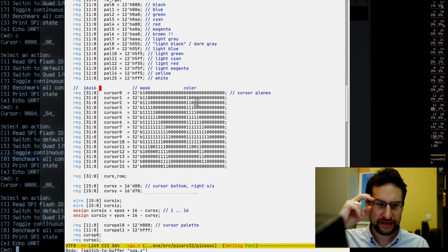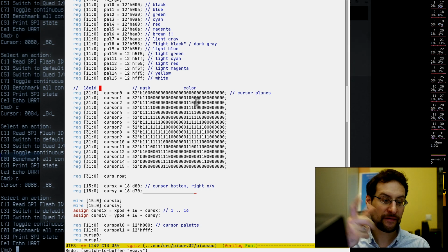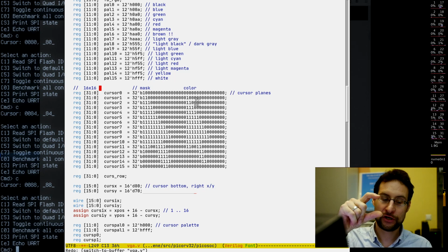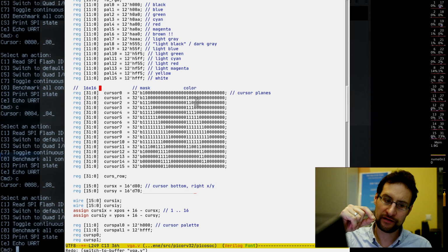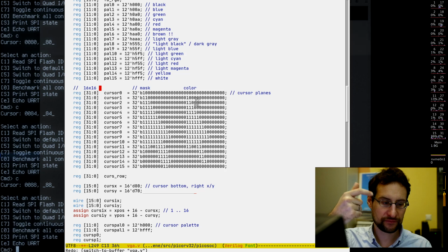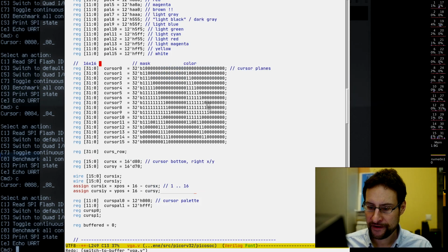So with this we can make a really super fancy blinking text cursor by just moving this hardware cursor to the location that we want this to blink, or we can have underline or full block and inverting, so super nice. We can even theoretically, maybe we do this later or tomorrow, have a block cursor and an underline, inverting the top 80% or something differently than the underline, or some fancy stuff there.